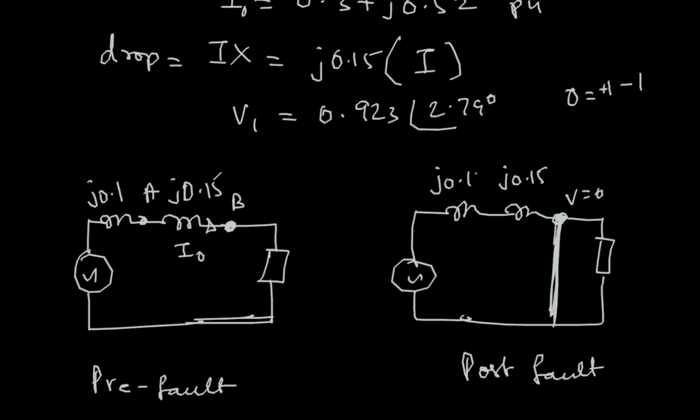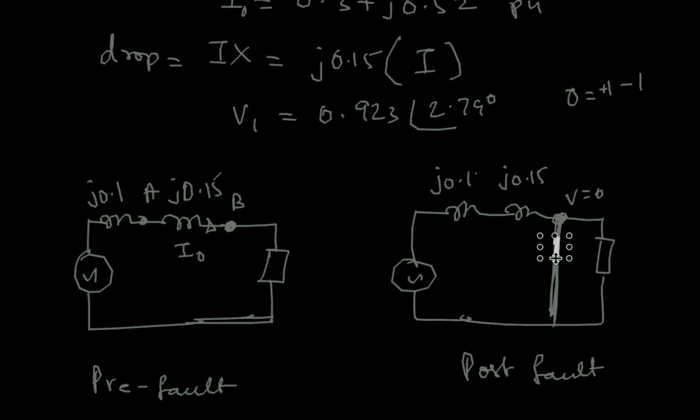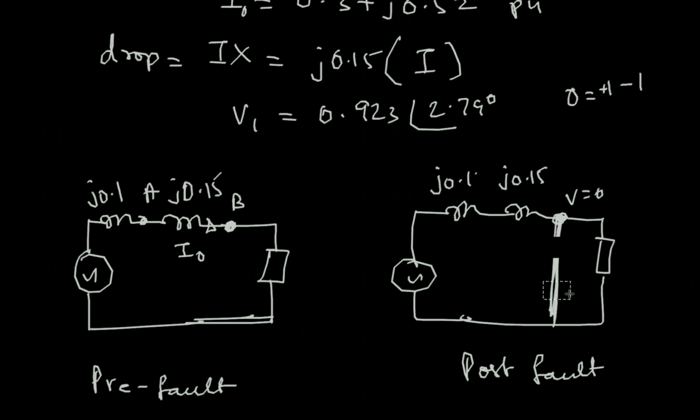So what I will do is I make two gaps here and then introduce two voltages like this, but here the sign is plus minus and minus plus, so the plus is here downwards. The voltage whatever it used to be here, that is V2, the same V2 I'll apply for both of these. So now this is post fault.